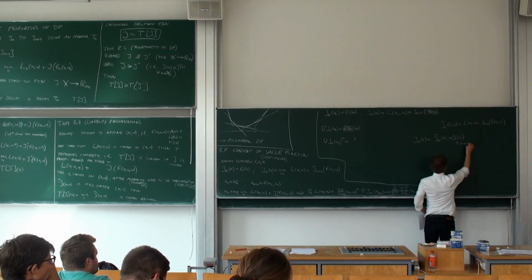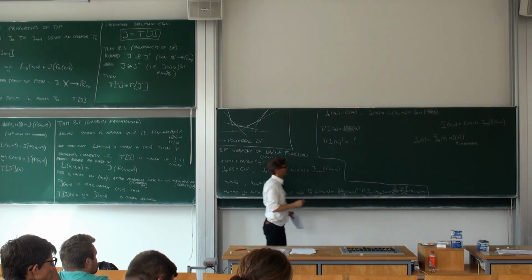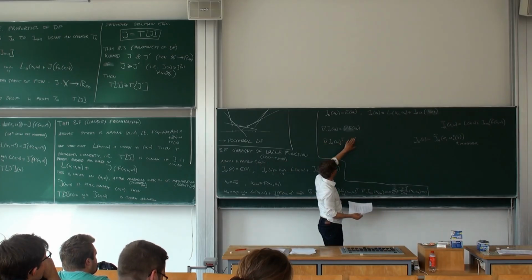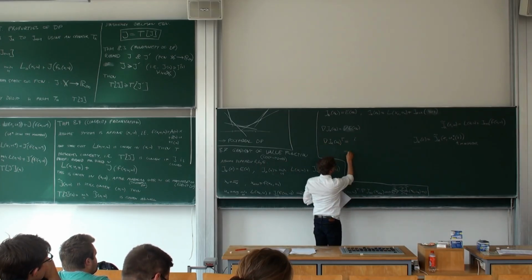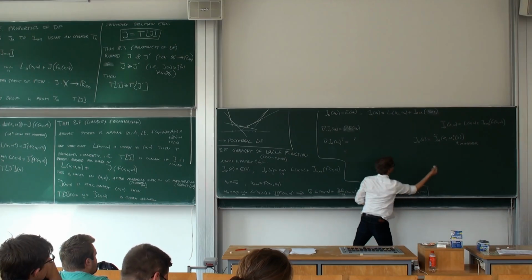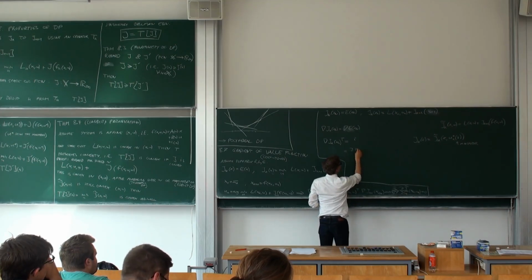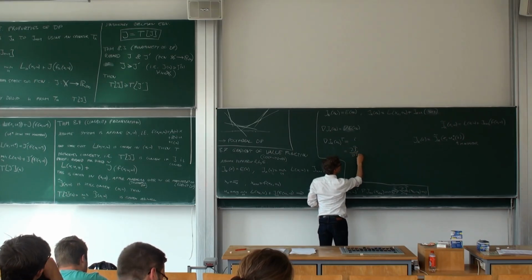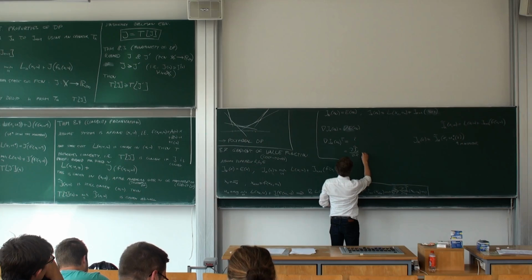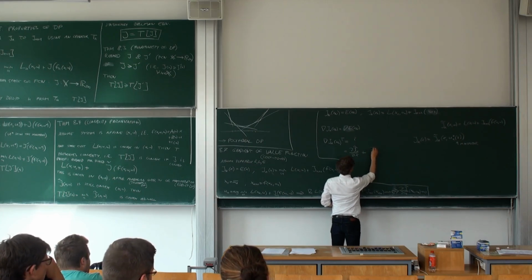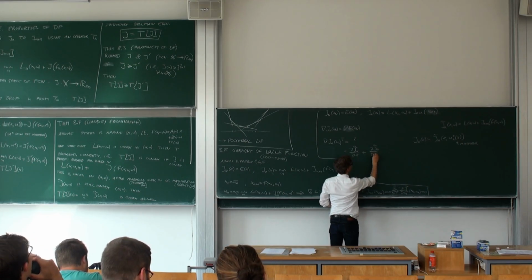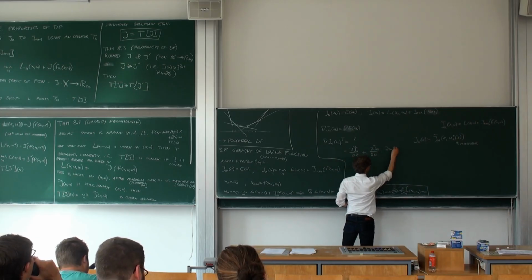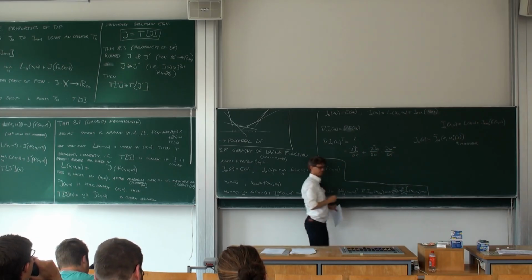So that's the minimizer of this problem. And now I could ask the question, what is the gradient of this whole thing at the optimal solution? And so what I can do is I can differentiate that whole thing inner and outer. So what I get is dj tilde k by dx, plus dj tilde k by du times du star by dx, right?